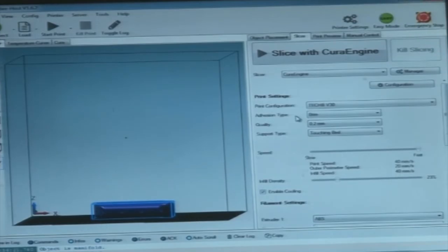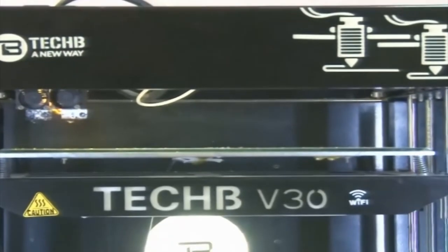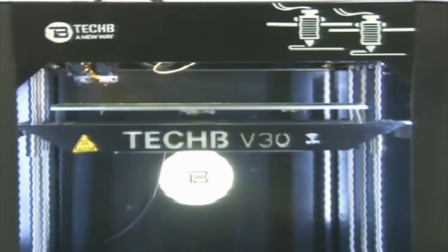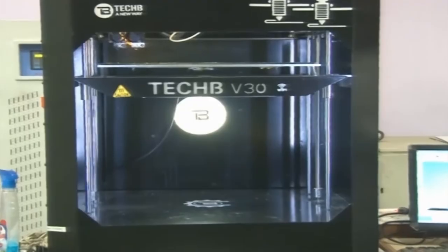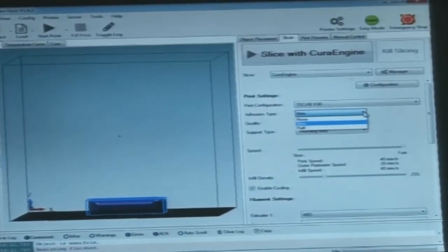This plays a very important role, because this layer will stick with the machine, this tabletop, this hot plate. If we do not provide any extra material at the periphery, the job may stick to the bed, and we may lose some features on the base of the job. So we use this feature only when we find that more material has to be added, when more area is necessary.